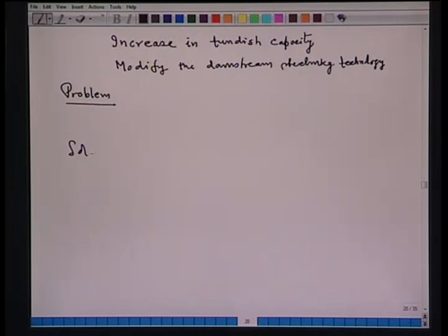What can be done? The first thing to be done is to increase the mold cooling. So, the solution is that intense mold cooling is required. Also, since steel melt flow rate has increased,